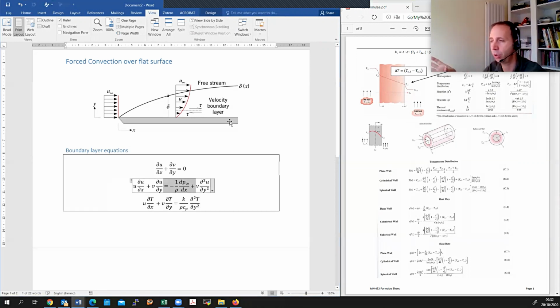And therefore, if you have a higher pressure in one region, you have to have a pressure gradient to get to that higher pressure. If the surface is truly flat, you may remember that the pressure doesn't change as a function of y. That's one of the results of the derivation of the boundary layer equation. Pressure is constant along an axis which is perpendicular to the plate. And we also find that the pressure, no matter where you position yourself, is not going to change as a function of x. That's for the very special case of a flat surface with an external flow.